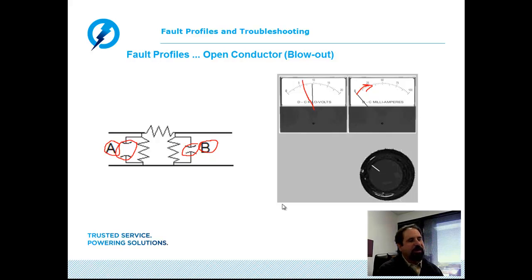Now, why do I make such a big deal of this? If you're having difficulty breaking down the cable fault, and particularly you're having difficulty getting good strong thumps or arcs established, listening for this fault when you go to do your pinpointing may be very, very difficult. If your thumper or surge generator is not breaking the cable fault over on every discharge cycle, again, that's an indication that this gap may be very large.